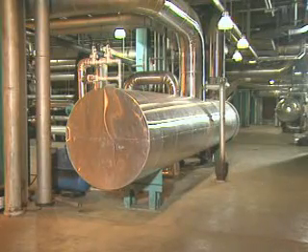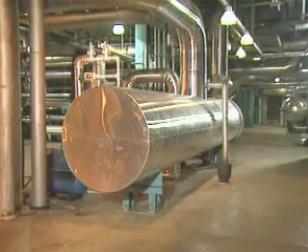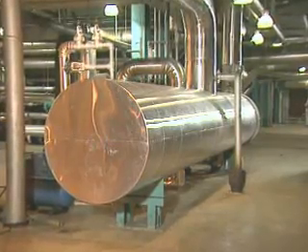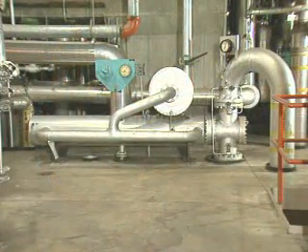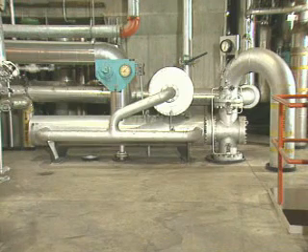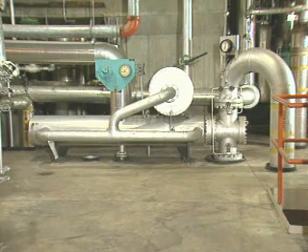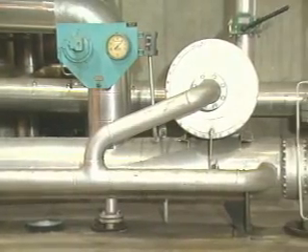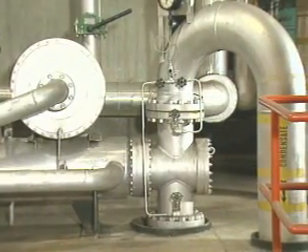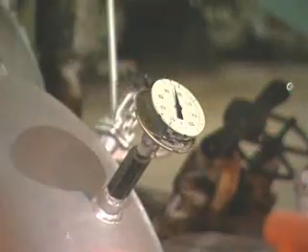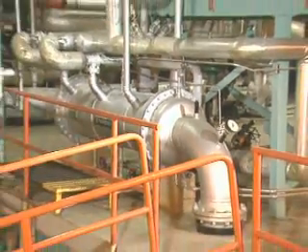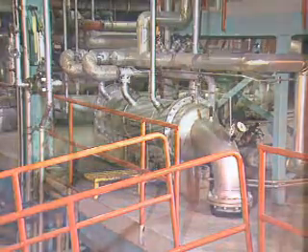A condensate and feedwater system also has several condensers and heaters. Most of these are some type of shell and tube heat exchanger. For example, the initial warming of the condensate from the hot well is achieved by using the condensate as the cooling fluid in condensers. Gland steam condensers recover heat from the steam used in the plant's gland steam system. Air ejector condensers recover heat from the steam in the main condenser's air removal system.